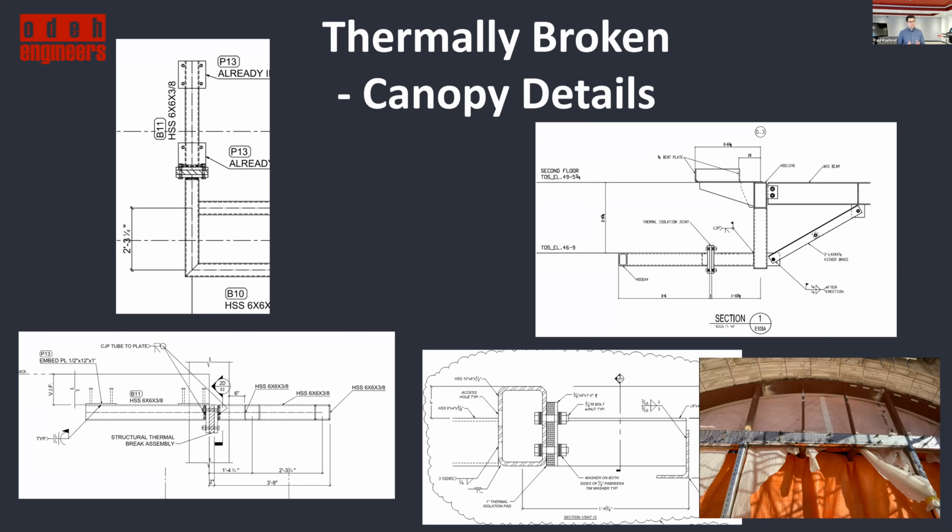most of the time with these details, you're going to have a bolted end plate moment connection. Now, most of the time, that's most achievable by having that plate extended above and below that tube with the bolts extended out there as well. And what I want to highlight here is the position of that connection needs to be coordinated with the positioning of your curtain wall assembly or your storefront.